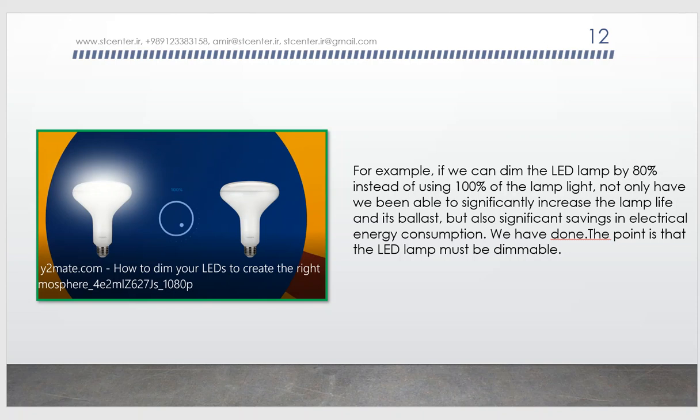During this job for dimming, we should notice that, for example, the human eye is not so sensitive to 80% or 100% light. Okay, so we can put the maximum light to 80%, and with this we can save energy. I mean, when we use the dimming actuator in the right way, because if you use it in a wrong way, you always lose the amount of light you needed. I mean, if you choose the wrong lamp or wrong actuators, it makes big mistakes.